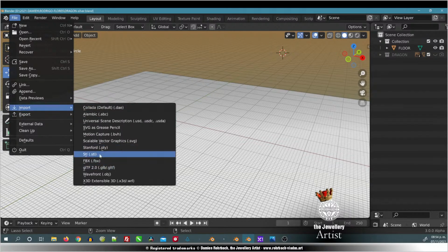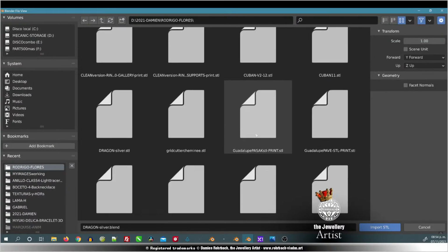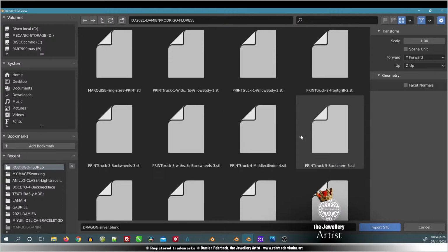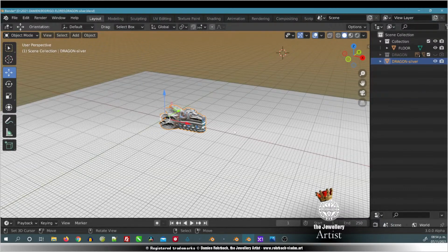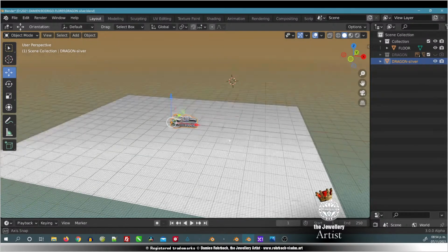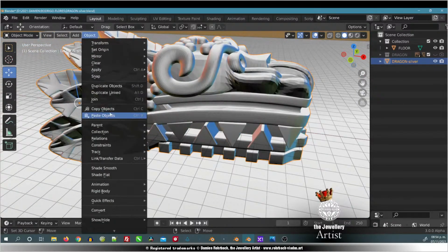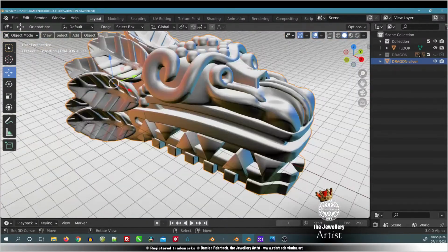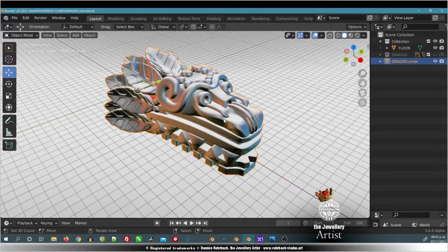So it's better to export the STL, test the STL, and bring the STL back and render the STL file, because it's a copy from the original, and if you harm that mesh, it's not that much of a problem. So I'm going to render this. So this is the STL file, and also now I know I can make the render and I know that the file is ready for printing. So now I can render the file and show.